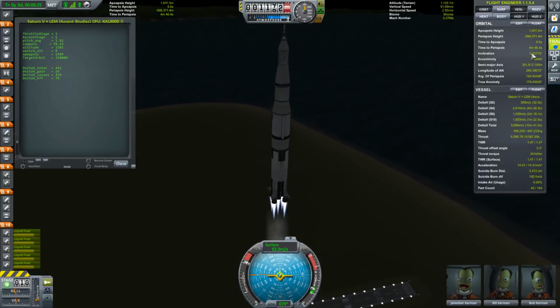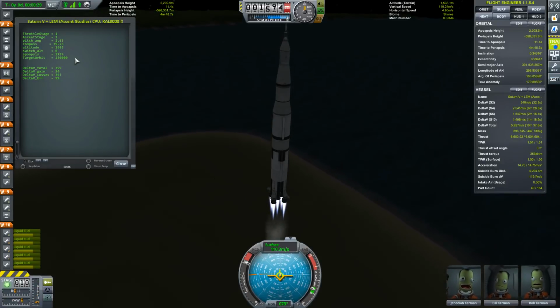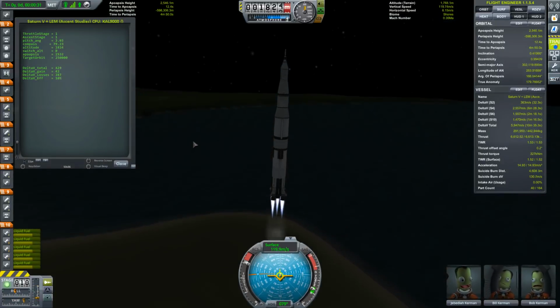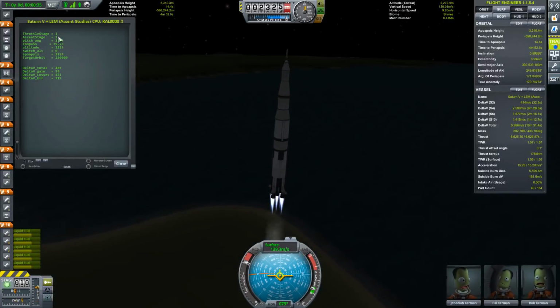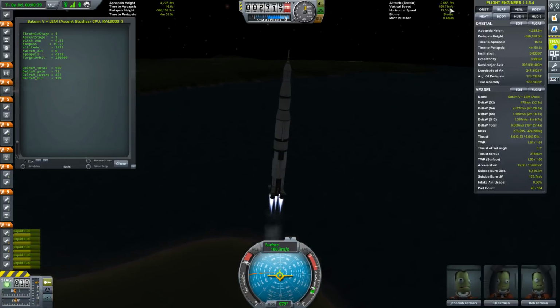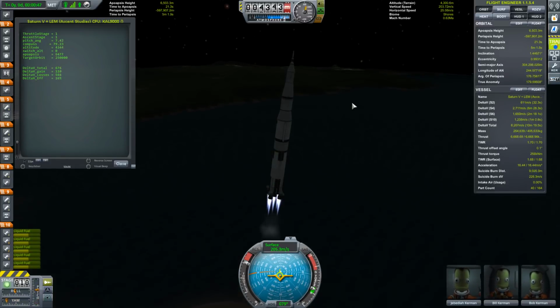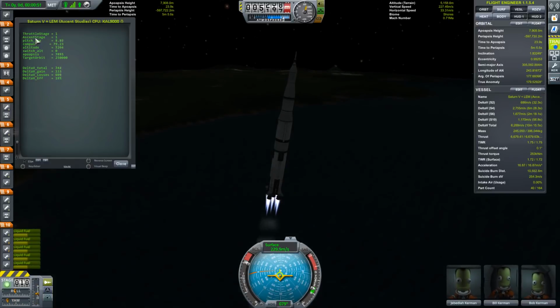So before it was just set to 0. Now we're going to try and hit 10 degrees inclination. And yeah, I mean that's pretty much all it's doing. So every time it's iterating, it's calculating the vertical acceleration. It's taking into account the vertical speed, seeing how long is it going to take for me to get from this point to 49 kilometers, and then pitch over so that I hit that pitch angle at 49 kilometers.